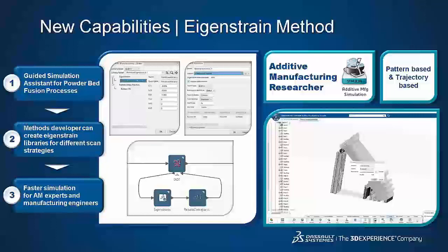So by providing both thermomechanical and Eigenstrain process simulations, we make sure that users at different enterprises with different accessibility of experimental and machine data can use process simulations based on their needs. For example, for an enterprise that has access to a built-up Eigenstrain library, using the Eigenstrain method could enable faster development cycles. For researchers who are looking at microstructure and complex deformation modes, the thermomechanical approach is a better choice.